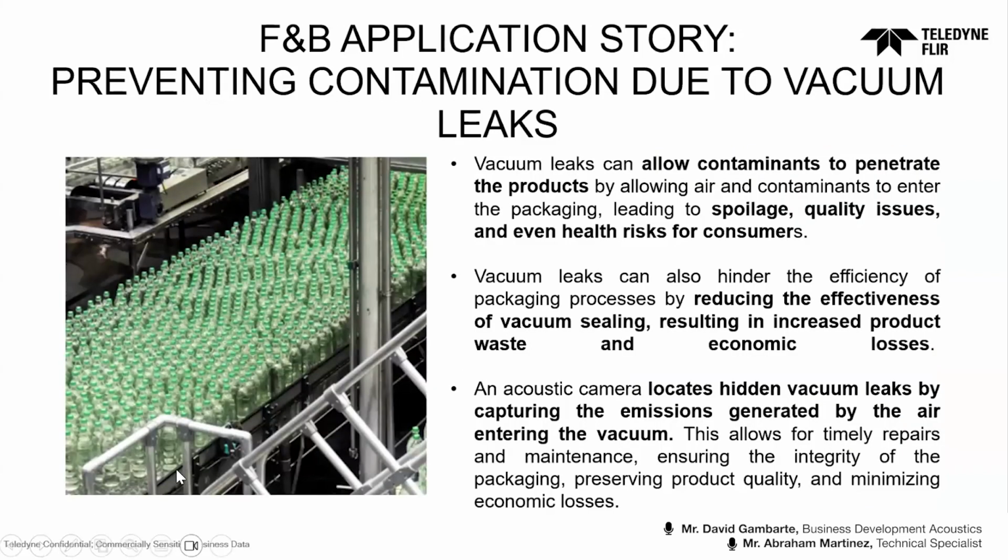There is another use case, which is preventing contamination due to vacuum leaks. Vacuum leaks represent a big issue in many industries, also in food and beverage, and allow contaminants to penetrate the products by allowing air to enter the packaging, leading to spoilage, quality issues, and even health risk for consumers. So we were mentioning this before.